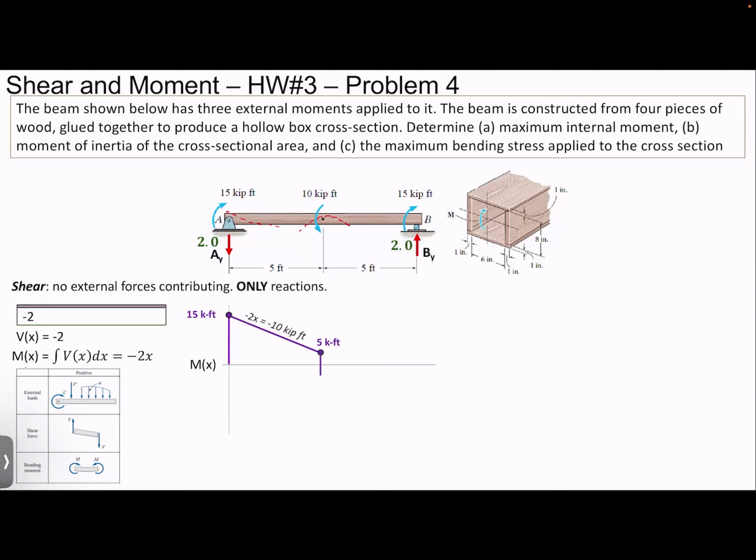And then this one is going to be causing it to go that direction, which is positive. So we have to make sure we keep those external moments the same direction. I say half pipe positive. If you want to just always remember clockwise is positive, you can also do that for external. But I think it's helpful to know the meaning behind that.